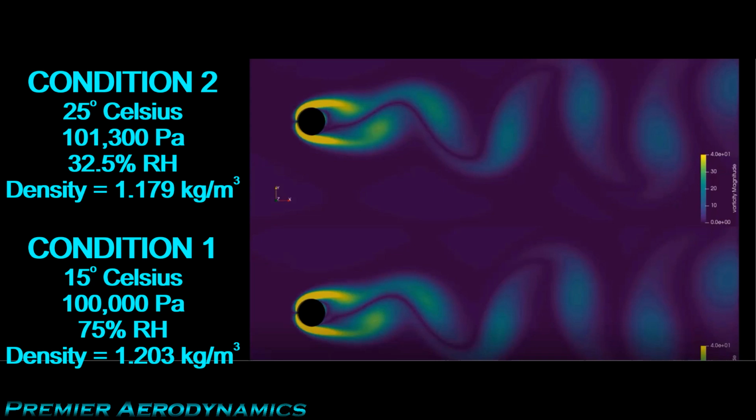And if you haven't learned about LSBs, I've done lots of podcasts on them. You can find them in our history, and you'll know after you watch them that the LSB is very, very sensitive to the Reynolds number. Even a 2% or 1% error in the Reynolds number will dramatically change where the LSB starts and ends.